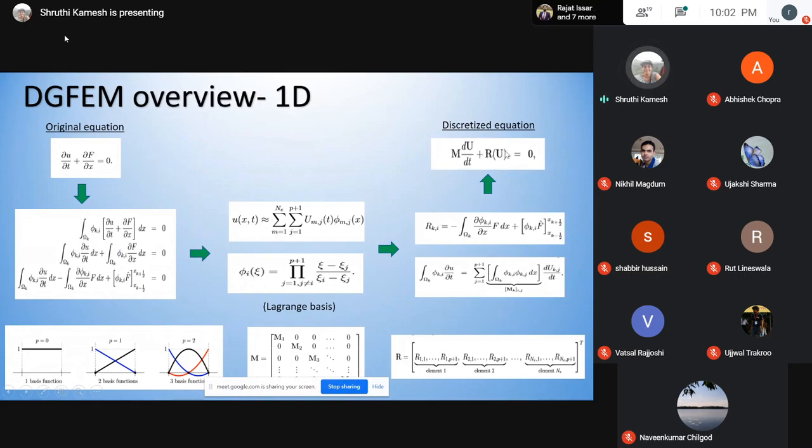You form these terms for each element, and then you solve it as a whole. Given your loop, you're marching through time, and you have your initial condition. You want to see how your solution looks at different times, right? So inside your loop, you form your gigantic mass matrix by assembling the element mass matrices over here. So you have this gigantic matrix, and you have this large vector of n times (p plus 1) unknowns.